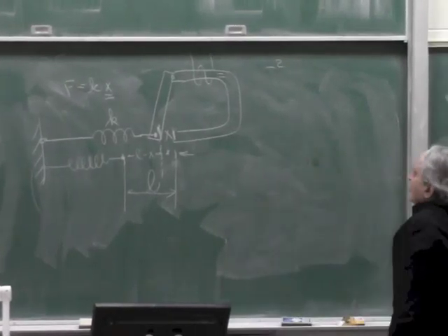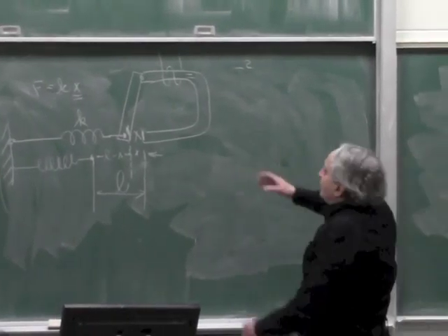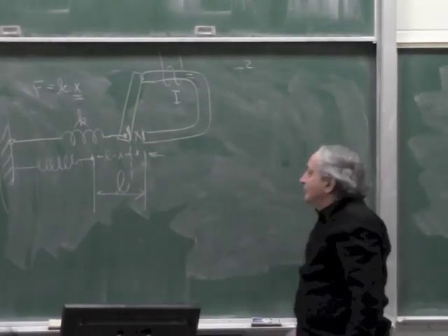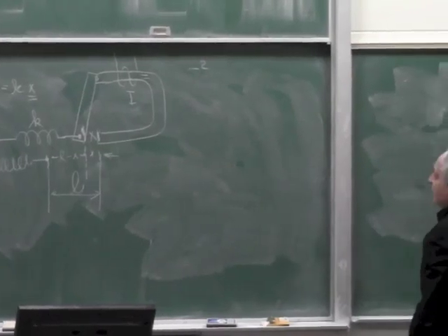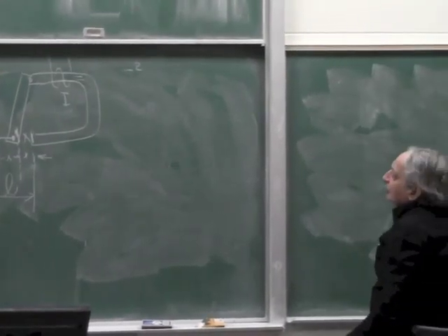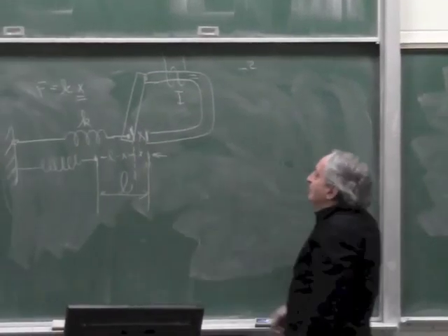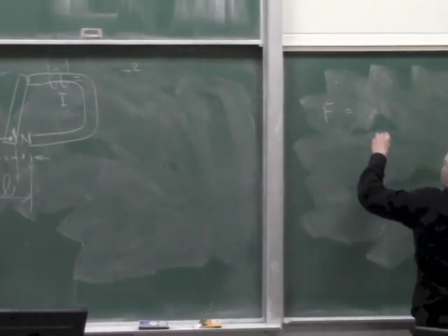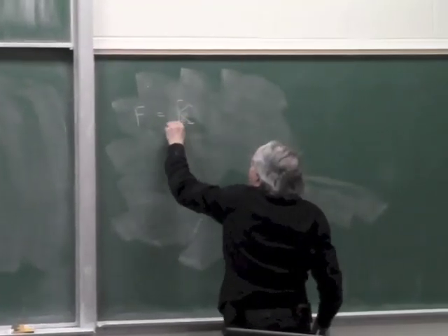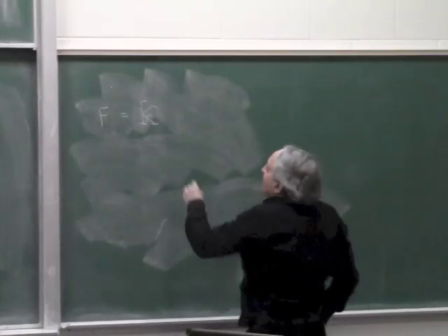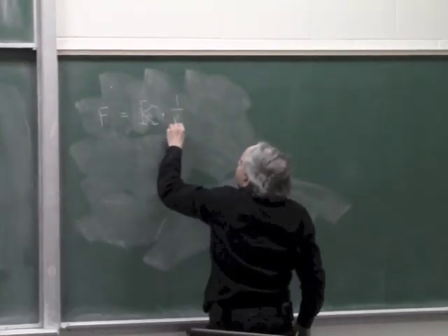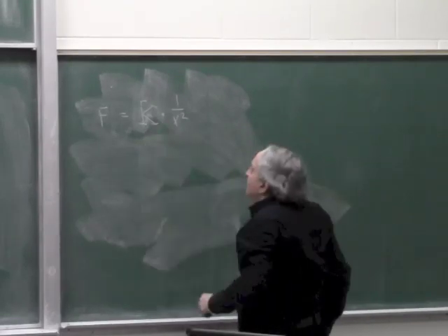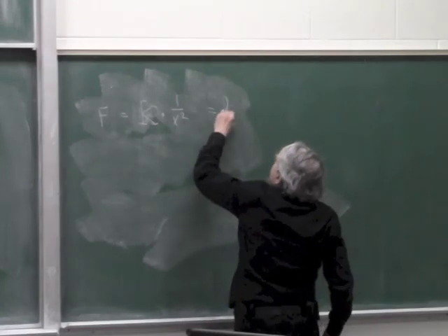Okay. So let's say it reaches equilibrium. At a certain current I can hold it at a certain position x. So obviously at this point I can say that the force of the coil, which we said is some big K, which I derived just a few minutes ago, times 1 over x squared, and this big K includes I and everything, has to be equal to kx.